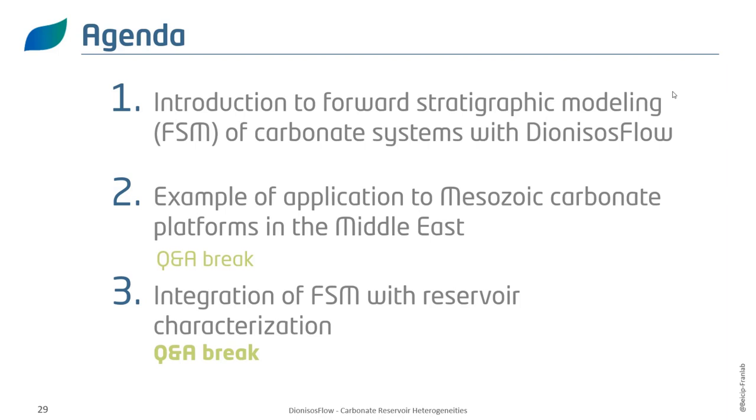But we also have the possibility to export in very different formats that are usually compatible with most industry standards. So just to add to that, we have the direct links and we have GRDECL and RESQML formats that will allow you to export. RESQML actually is the best format to export your grid and re-import it. It's an industry standard that has been discussed with other companies, so you should normally be able to import it within any software.